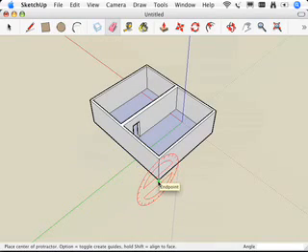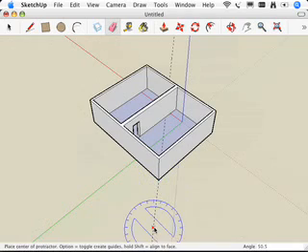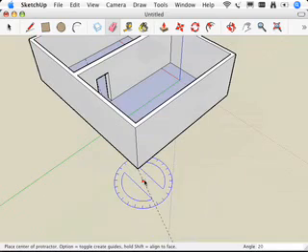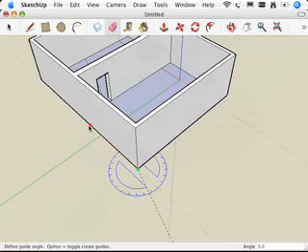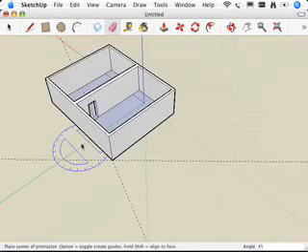When I click on the center of something, and then I click again, and then I click, what it's letting me do is actually draw a guide based on an angle. So let's say I wanted to draw a guide that was, see the little angle showing up here, a guide that was 20 degrees this way. I'm just going to move this over and then type in 20 and enter. And now this guide is exactly 20 degrees from this line that I had imaginarily drawn. Let's do another one over here. Let's draw a guide that's 45 degrees from there.